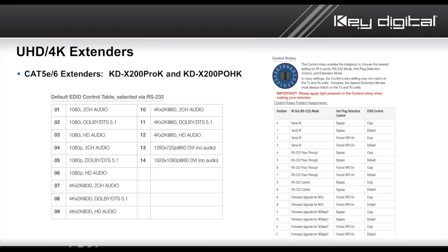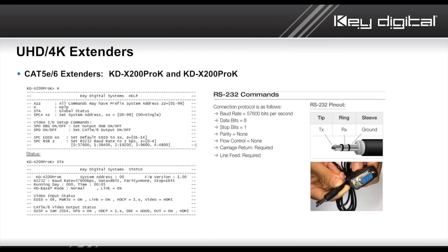That's no problem. But what if you wanted to set it up to 4K 30 or 4K 60 in our product as our default, our internal software? You would have to send us an RS-232 command to adjust that. Here are all of the RS-232 commands we give you for the X200. That's right, these Baluns don't only extend control, they are controllable devices. The transmit unit of all of the products you'll see here today, fully controllable.